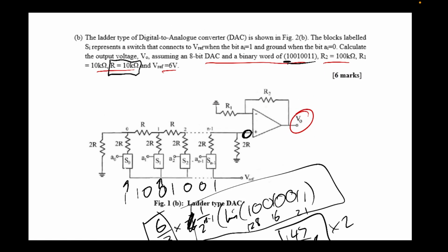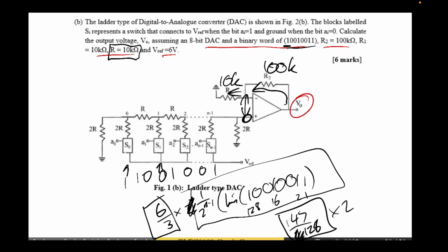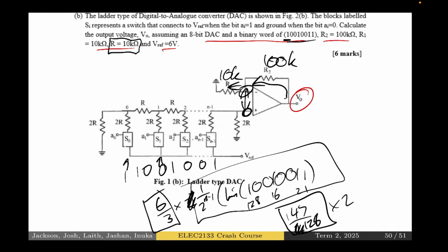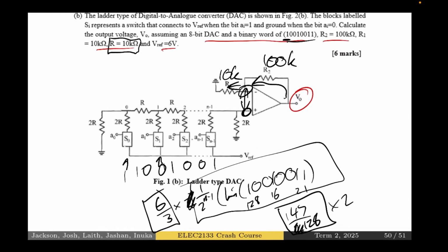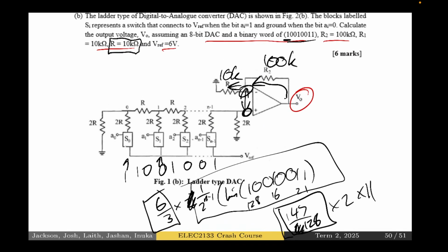Okay. So that's V plus. Then we go ahead and we do the non-inverting op-amp. We know it's a 100K to 10K, and if we ever get in trouble and forget the formula, we can just recognize that, okay, same current going through, we know these two voltages are the same, and oh my gosh, same current through 10 times the resistance just multiplies it by 10 to that point, so total, you get times 11, essentially, because there's 11 times the resistance for the same current. So then times 11, and that would give me my answer as Vout.